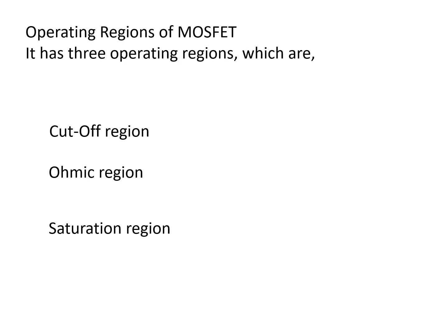Now, the operating regions of MOSFET. It has three operating regions, that is cutoff region, ohmic region, and saturation region. In the cutoff region, there is no conduction, due to which the MOSFET will stay off and behave like an open switch. In the ohmic region, the current increases with an increase in voltage value, and MOSFETs operate in this region when generally used as amplifiers.